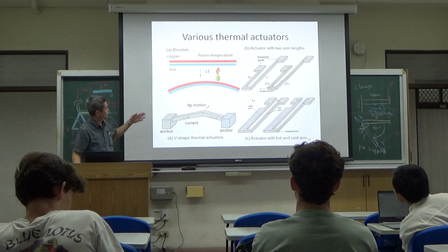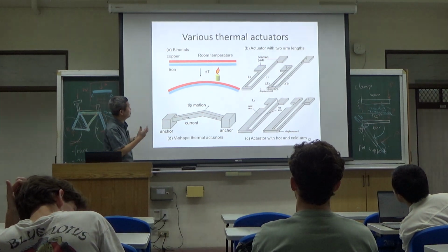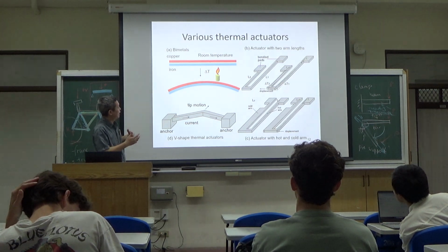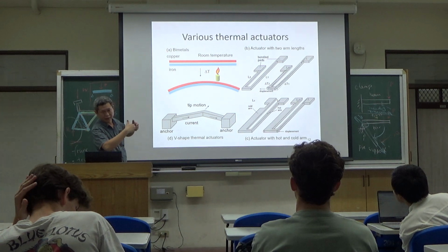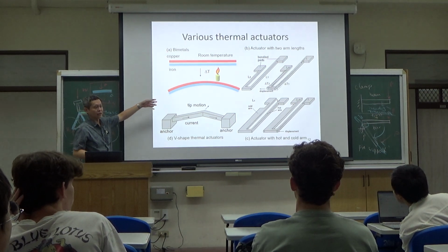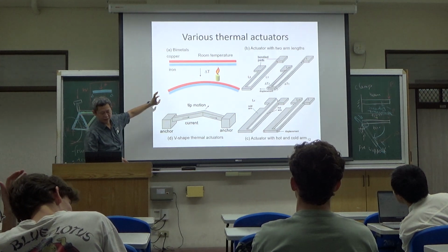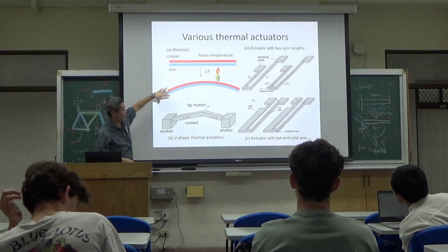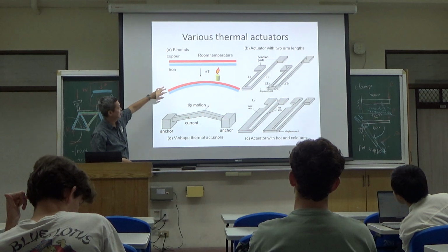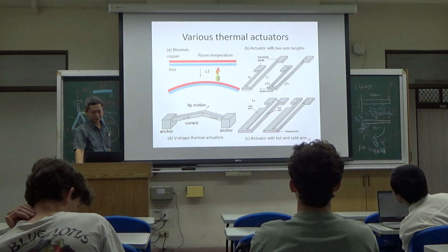So the bending of a bimetal strip happens because of the differential expansions, and that difference in the axial elongations will be converted into bending. So that's why again this structure should be considered as a frame structure. It's a combination of bending as well as the axial expansion.